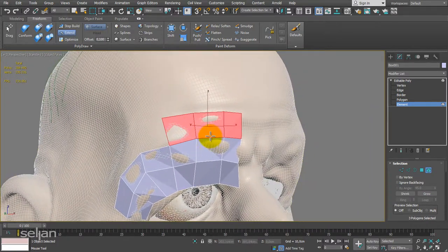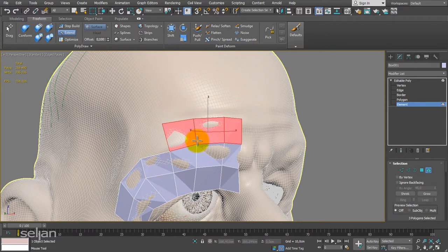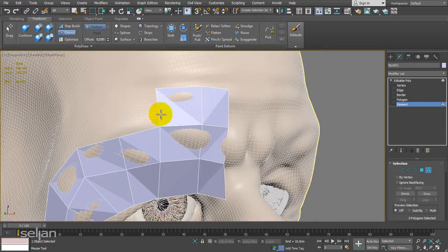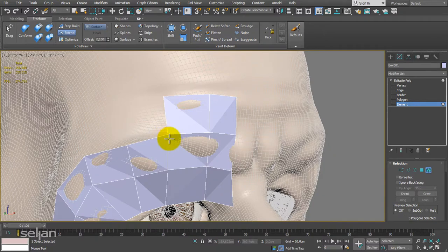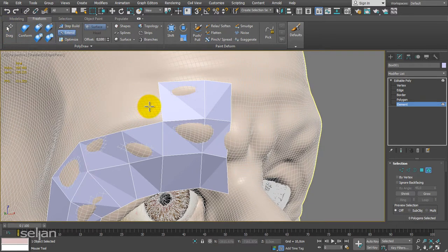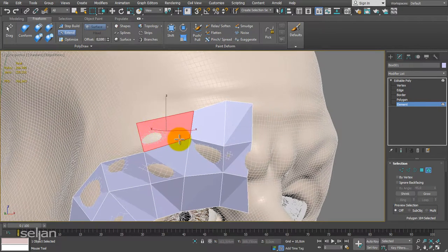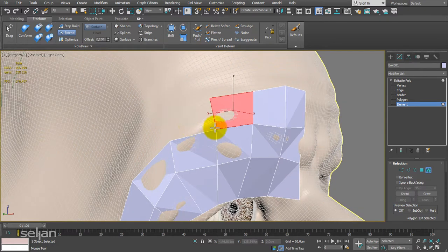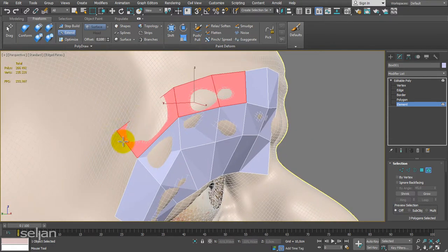Now what happens if you want to make a correction other than delete? Again, deleting is by holding control and tapping on a polygon. We are still in extend mode. How to manipulate the vertex if you want to change the position of the vertex and you don't want to go to drag. So this is what you want to do, but you don't want to leave extend. Then you are using the Ctrl Shift and Alt combination. So I'm using Ctrl Shift and Alt all together, and the left mouse button, and now I'm ready to move. So it's pretty fast. Make a correction, move it away, okay, and again holding down nothing, just dragging it out. Here we go, this is what we have.